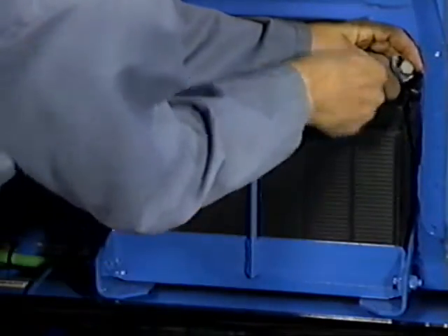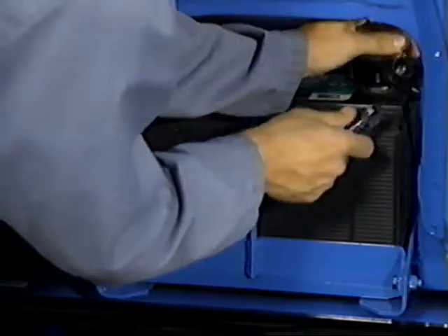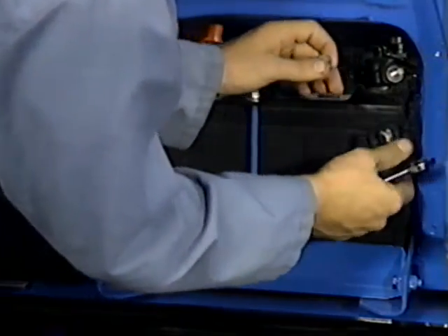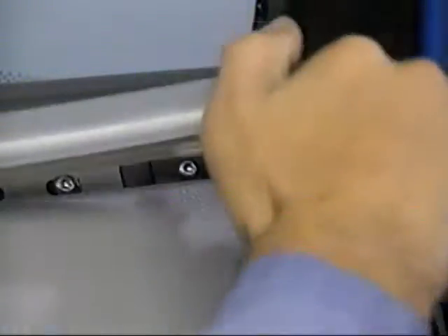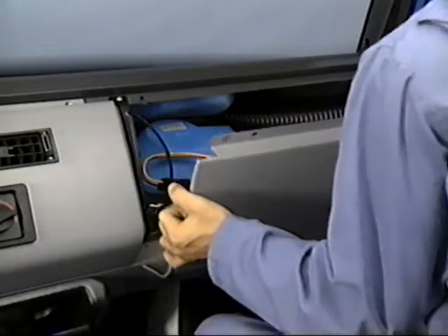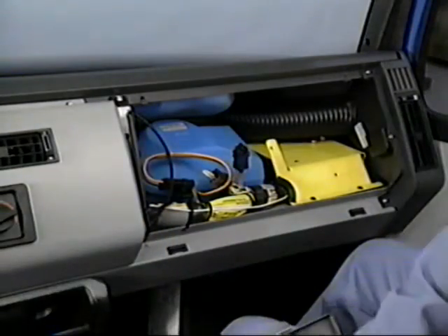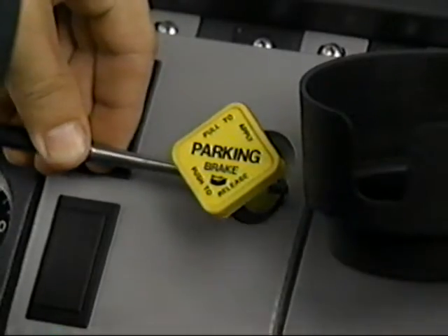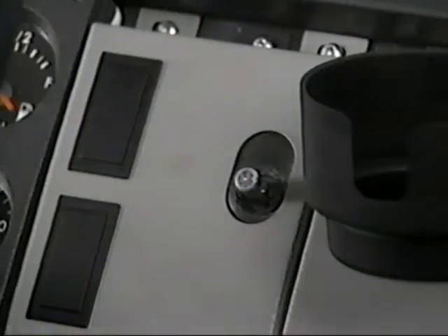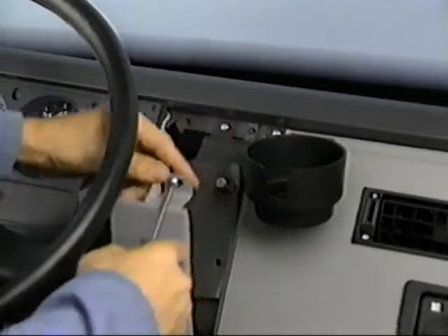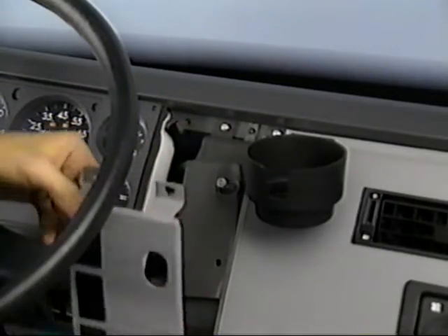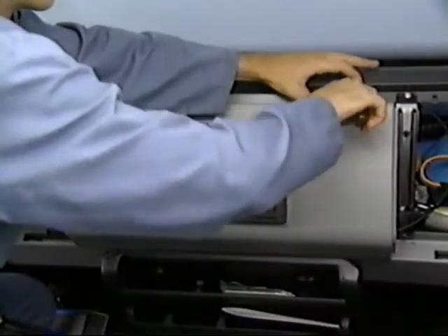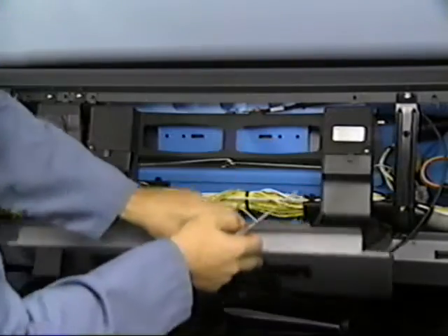Before removing the heater AC control panel for replacement of the panel or other repairs, disconnect the vehicle's batteries. Remove the extruded rubber strip at the top of the dashboard, and then remove the dash panel at the far right on the passenger side. After removing the parking brake knob on those vehicles with air brakes, and if so equipped, the trailer air supply knob, remove the small dash panel to the left of the heater AC controls. Now open the dash panel which surrounds the heater AC controls.